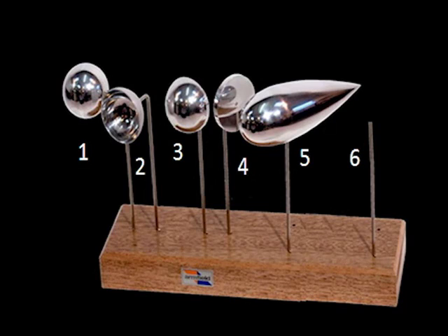5 drag models are included in this experiment that have the same equatorial diameter: sphere, convex to air flow direction, concave to air flow direction, circular disc, streamlined shape, and spare support rod for drag calibration purposes. In this experiment, the similar equatorial diameter drag models will be tested at different airspeeds using 0 angle of attack to have a direct comparison of their drag coefficients.